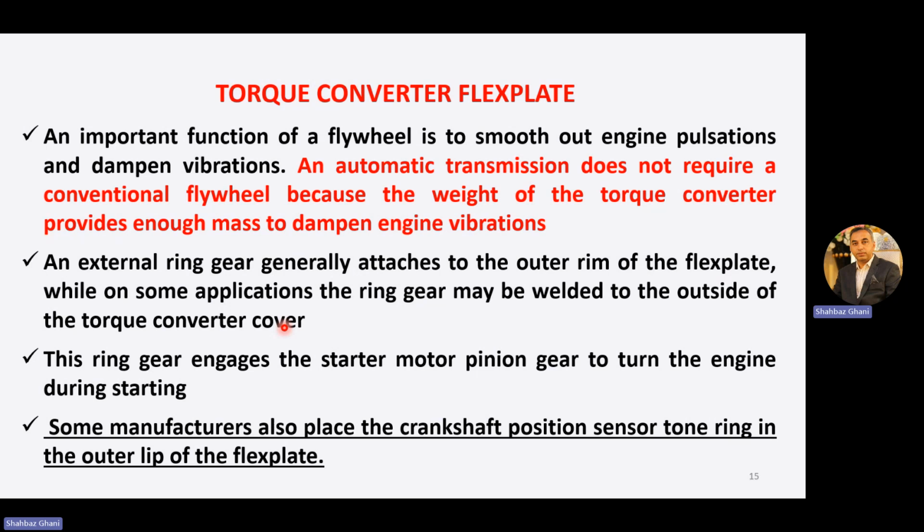What is the function of this ring gear on the outer rim of the flex plate, or welded on the torque converter cover? This ring gear engages the starter motor pinion gear to turn the engine during starting. It is the same function as the teeth on a flywheel, where the starter motor pinion gear turns the heavy mass of the flywheel in conventional vehicles. So the same goes here.